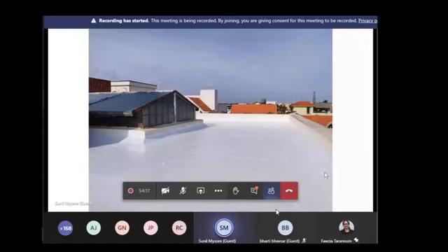What you can see on the screen is an ideal catchment. It is clean, it is white, it is accessible. This makes a good roof. Since there are some people from apartment communities, there is a tendency to lock up the roof so that people don't go there. I don't think it's legally right in the first place, because you can't keep the roof locked because of fire safety norms. Also, if you keep it locked, nobody will go to inspect it. If you keep it open, people may misuse it. So you must somehow draw a line. Then you can easily maintain that roof, and at the same time it is not misused.